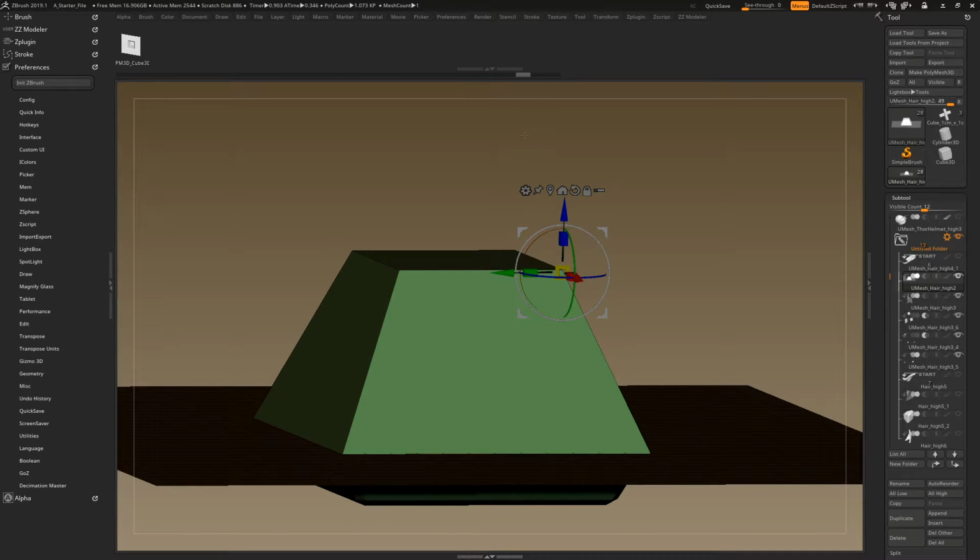You can't do it if you try and do it all at once. Well, I do it all at once, but this is a process. It's not one size fits all. Not in this case, but it is a form of standardization. And there's 2 types of keys, and there's 2 types of alignment tools for 3D prints. For FDM, I use pins, and those are standardized, as in they're always the same. For SLA, I use keys, and the keys are dependent on the size of the part.